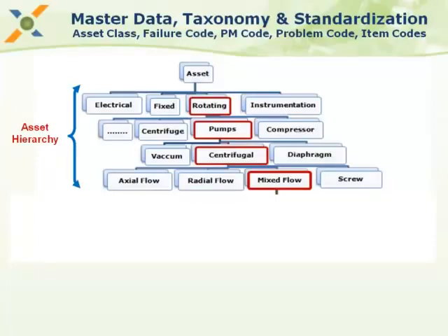That allows you to analyze how many work orders we have, how many failures we had, how much labor hours we are spending on which type of asset category, what are my critical assets, and where we are spending the most money in terms of maintenance budget on emergency problems or corrective maintenance. All of this can be done if we have a good asset hierarchy and can roll up with it.